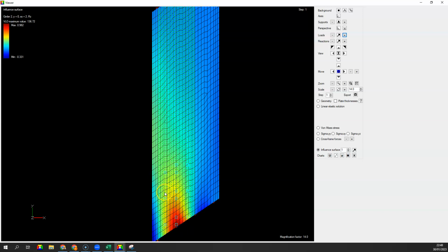You can see 6 point loads here and 6 point loads there. So here the multiple presence factor would be 1. And of course, because the influence surface is positive here on these 2 design lanes, the whole length here is also loaded. So here the maximum reaction would be 136 kips.